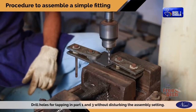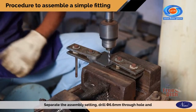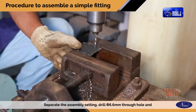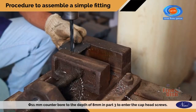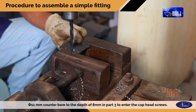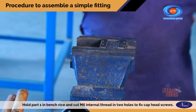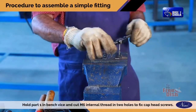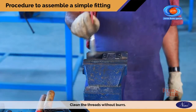Drill holes for tapping in part 1 and 3 without disturbing the assembly setting. Separate the assembly setting, drill diameter 6.6 mm through hole and diameter 11 mm counter bore to the depth of 8 mm in part 3 to enter the cap head screws. Hold part 1 in bench vise and cut M6 internal thread in 2 holes to fix cap head screws. Clean the threads without burrs.